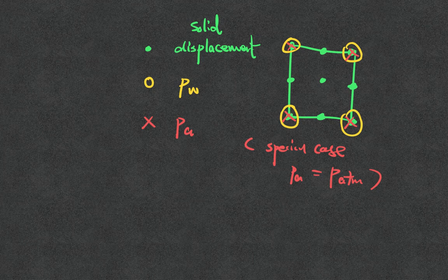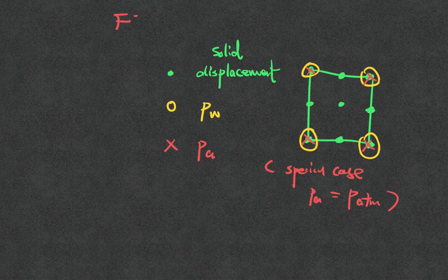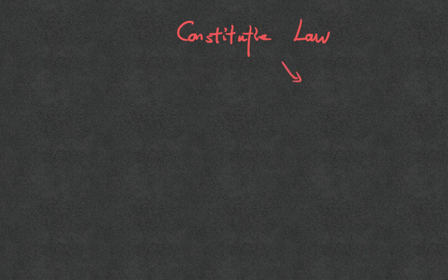Okay, so this is the final element. Now with the final elements, what we actually need to do is to list all the facts. Now I have the balance law, the rest is the constitutive law. So I will put the constitutive law into two. One is really the material law. Another one is the effective stress principle.